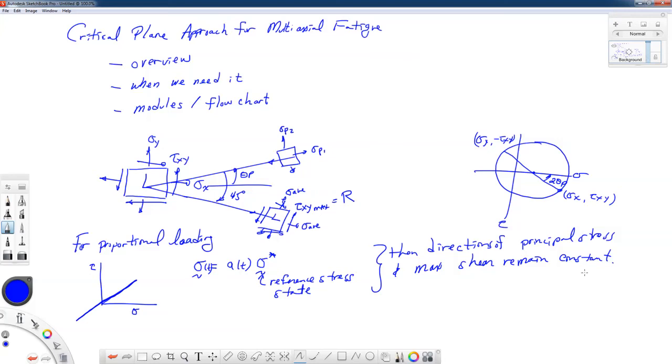Some materials are even sensitive to normal stresses and shearing stresses, depending on how small little fatigue cracks are or the slip systems are. So this can even change with the amount of life fraction that you've already used up for micro crack initiation and micro propagation. Very small development of very small cracks.